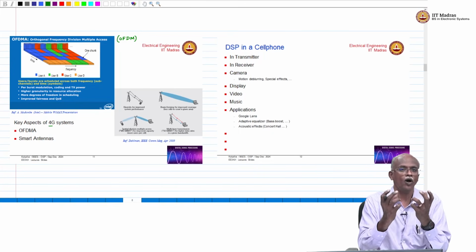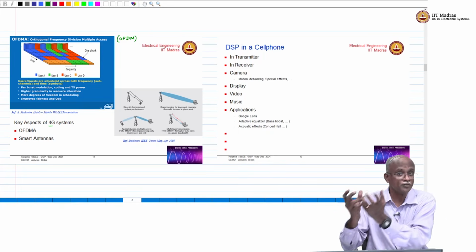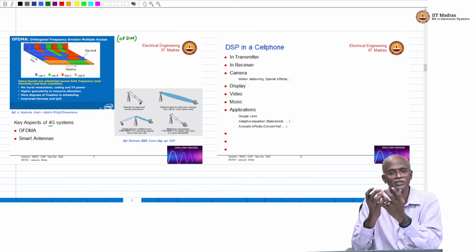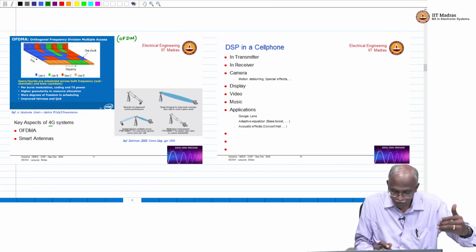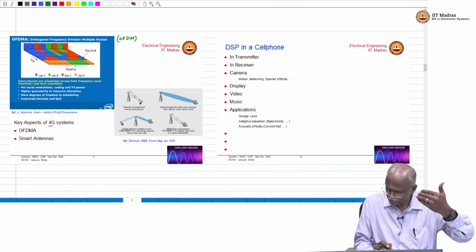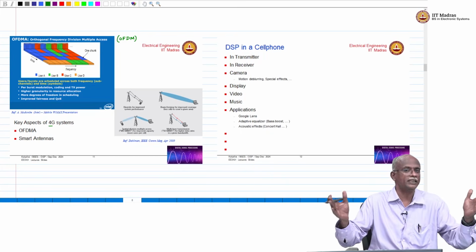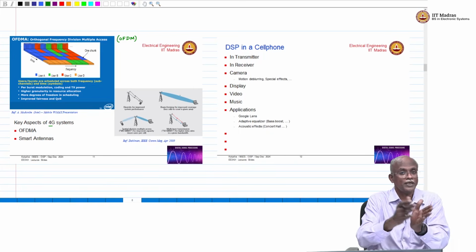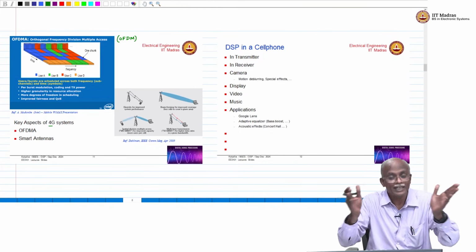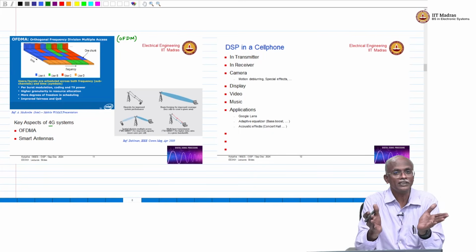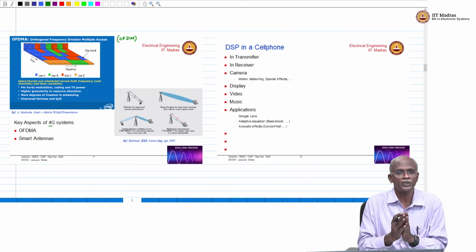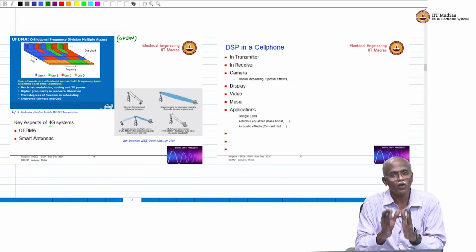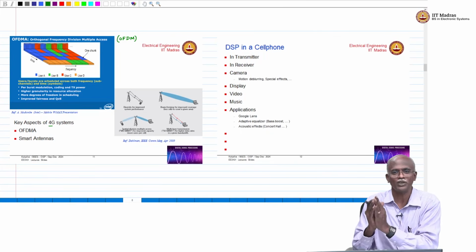So at the heart of a 4th generation system or a 5th generation system, you will find that the modulation method is OFDM, which is based on the FFT. Now, if you move to saying where else can I find multiple antennas, we use them in a 4G system for beamforming, spatial multiplexing, and multi-layer transmission. Now, all of these, along with diversity transmission, all four of these methods of using smart antennas involve signal processing of different types.